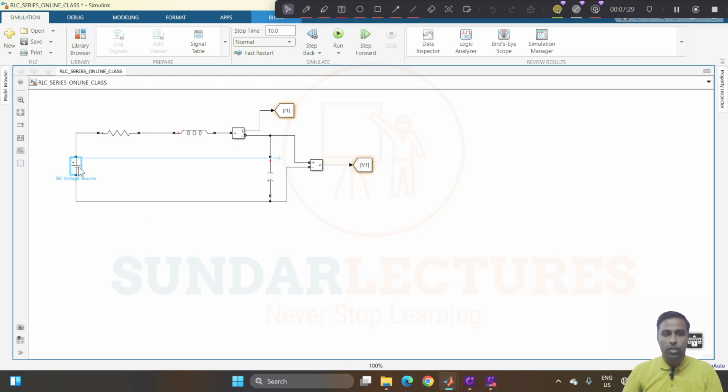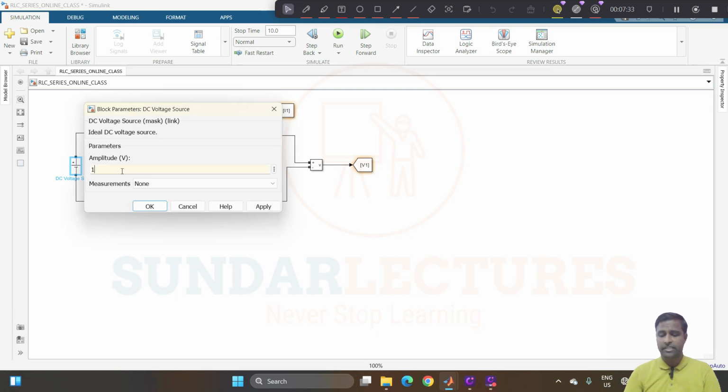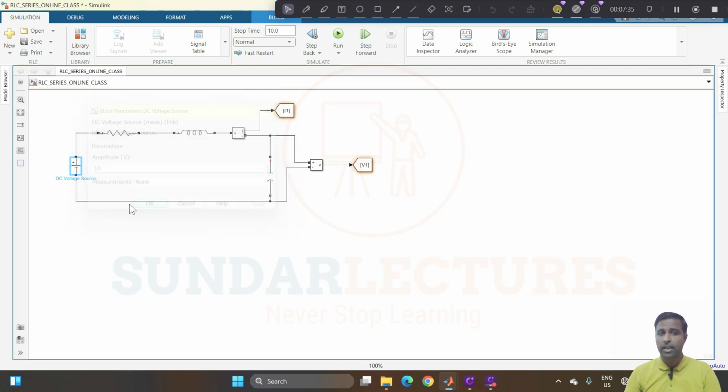And here what you do, go inside, what is the voltage value we have taken? It is 10 volt, right? So you put 10 volt and give it as OK. Then you see this first, what is the first case? First case, what we have taken, it is over damped, and the second case is critically damped, and the third case is under damped condition.